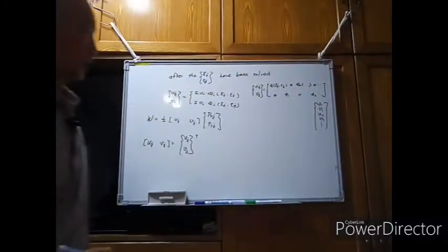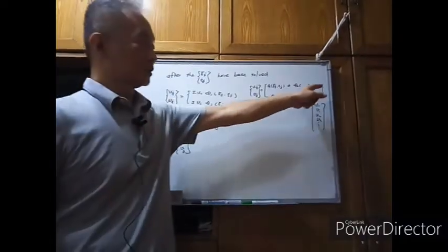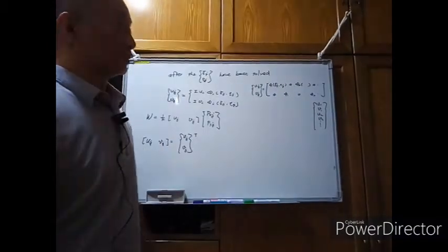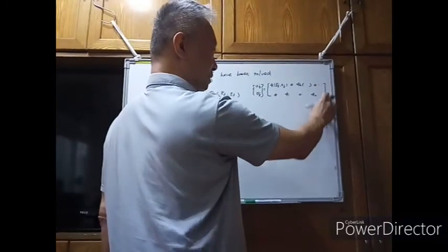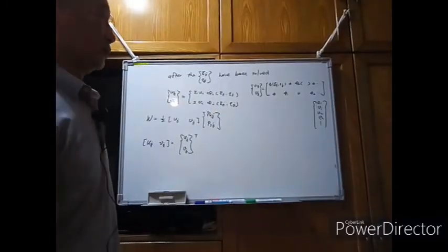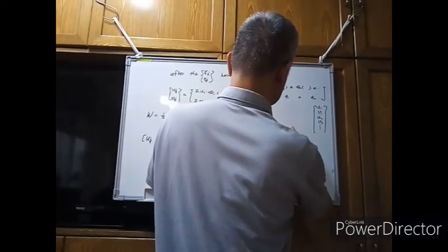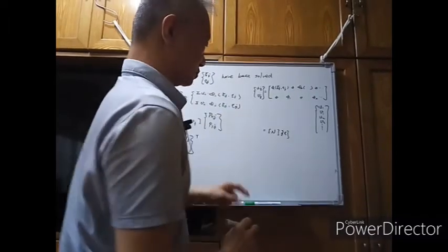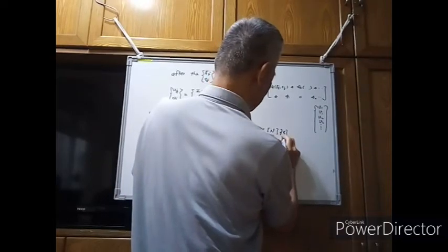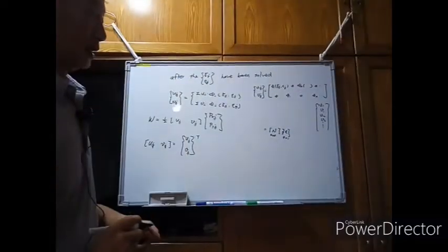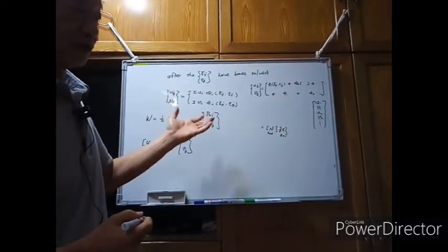Okay, uj and vj, if we use these two formulas and write them in matrix form, it will be a 2 by 8 matrix multiplied by the 8 by 1 vector. Sometimes we say this is the N vector times the u displacement vector. So N is 2 by 8 and u is 8 by 1, since right now I have assumed it is a 4-node element.